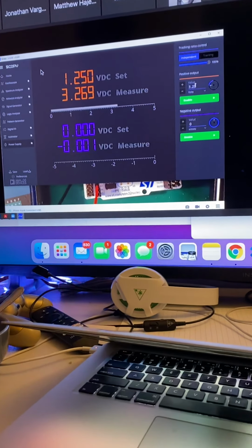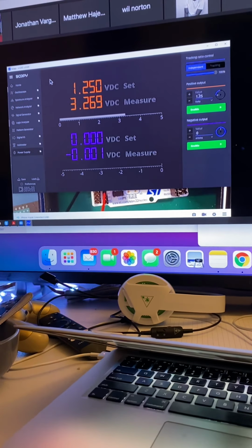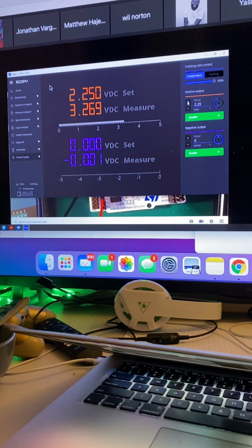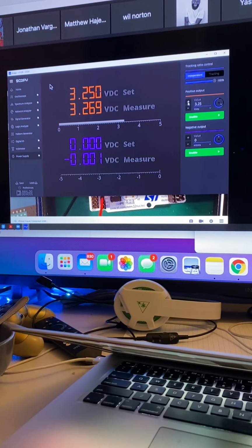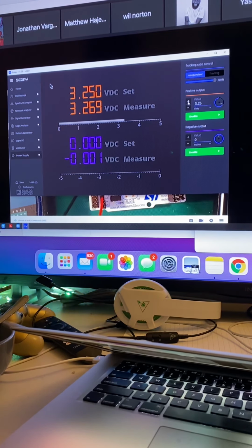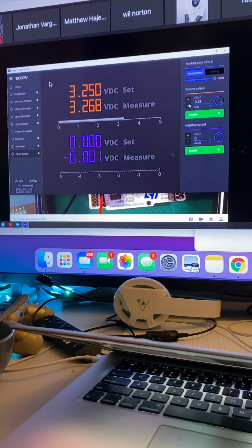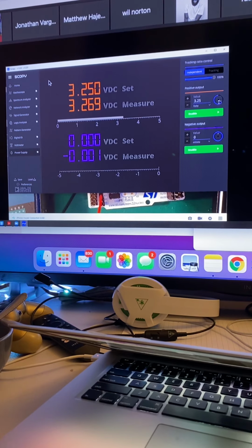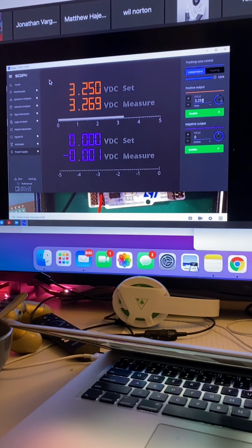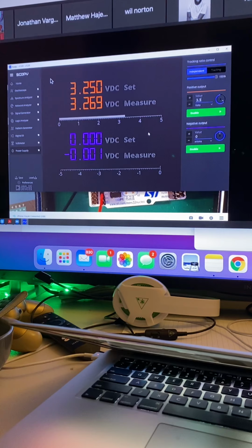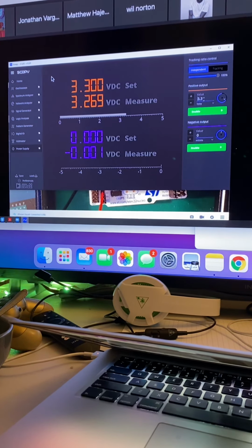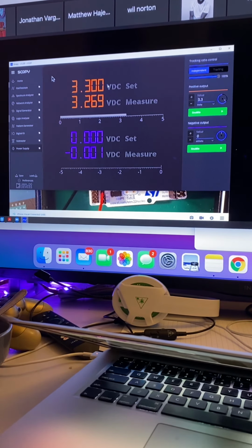So I would actually type in the value that you want. And the reason that I would do that is that if you're using the plus key, it's really quite easy to make your voltage go over 3.3 quickly without thinking about it. And if you use the knob, it's also easy to get that voltage outside your allowable range quickly without thinking about it. But if you're typing things in, you've at least got the ability to type it in, look at it, and go, that's wrong, before you hit enter. So it makes it a lot harder to screw things up.